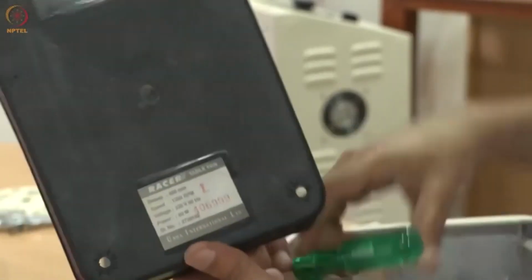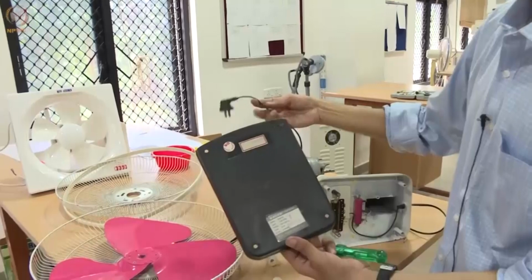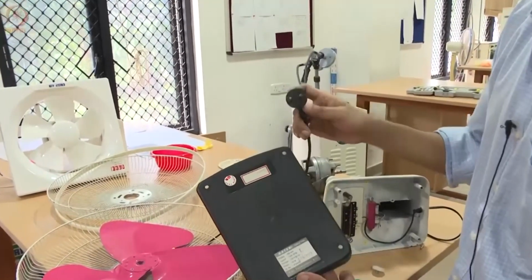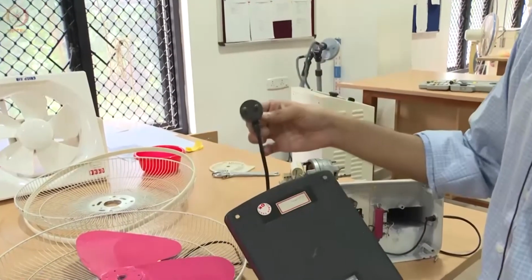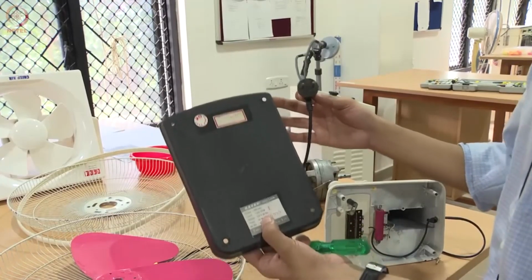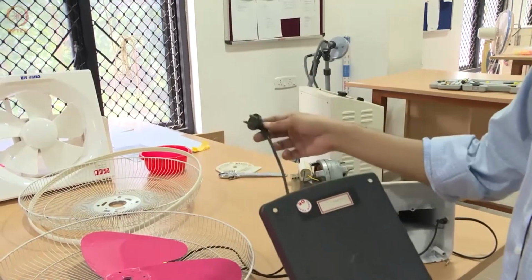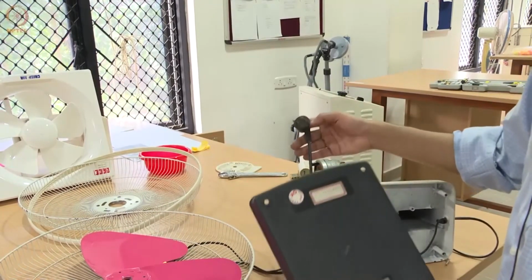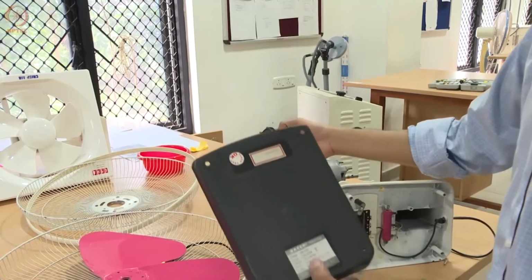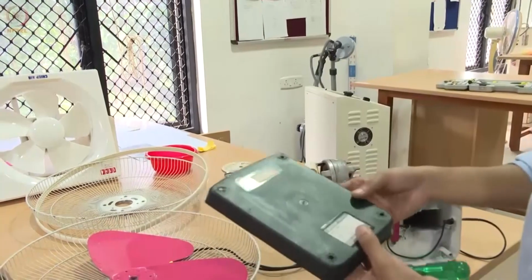The reason is, you should always plug the appliance into an outlet suited to its rated power. For instance, this fan draws less than 1 ampere of current when it is operated, which means you can comfortably plug this into a 5 ampere outlet. If the power rating of your device is much higher, let's say it crosses 5 amps, then you may need an outlet that is suitably sized.